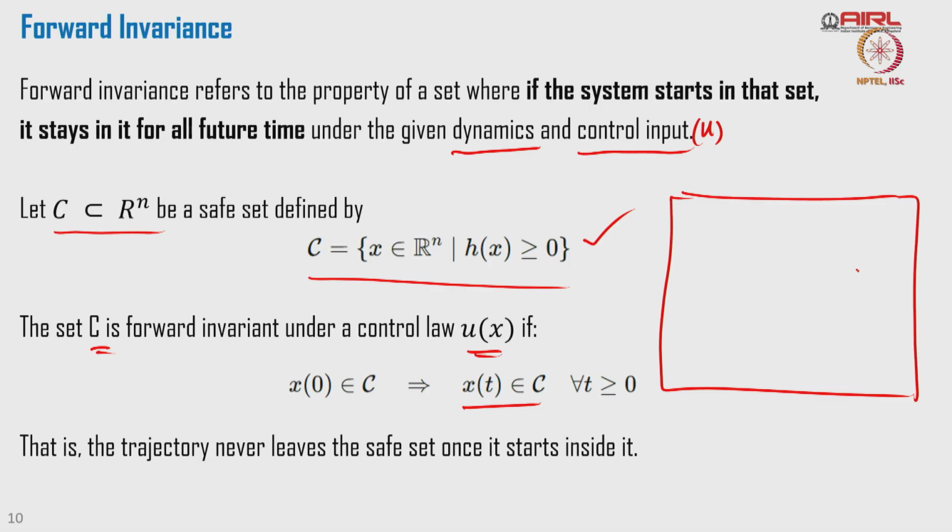Just assume that this is the obstacle. So this is the safety tolerance. Okay. Now our objective is to keep the drone in a safe set, right? What is the safe set? It is the entire set, say A, excluding this particular set, say this is some set S. Okay. So the set C we are talking about is the set inside, which excludes this set S, that means the tolerance region and the obstacle itself, from the main set A, right?